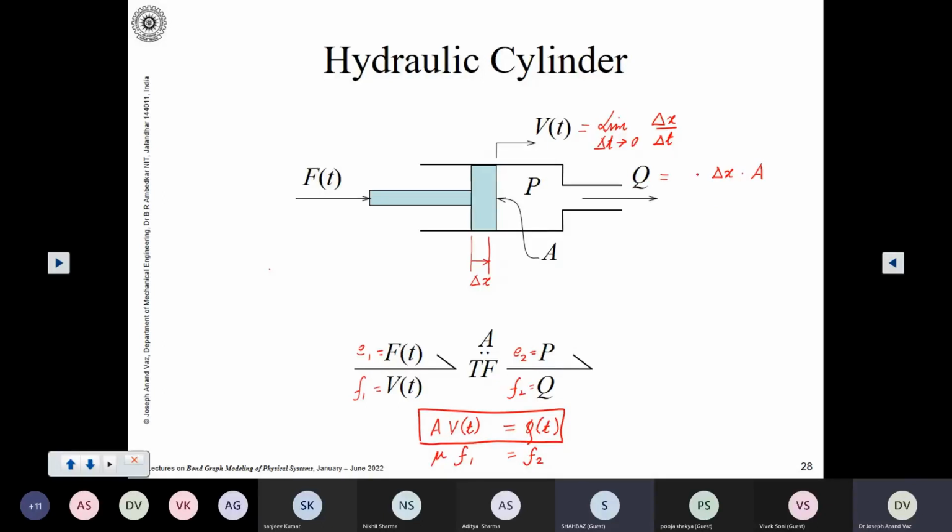Okay. And because it's the flow rate, you have to take the rate of the flow, so this is divided with respect to time. Now what you observe here is this is actually just the velocity, this part. It's just velocity. So you are left with Q is equal to A into V. Q is equal to A into V. I hope now it's clear to you how we got this modulus A. Yes, sir. Okay.